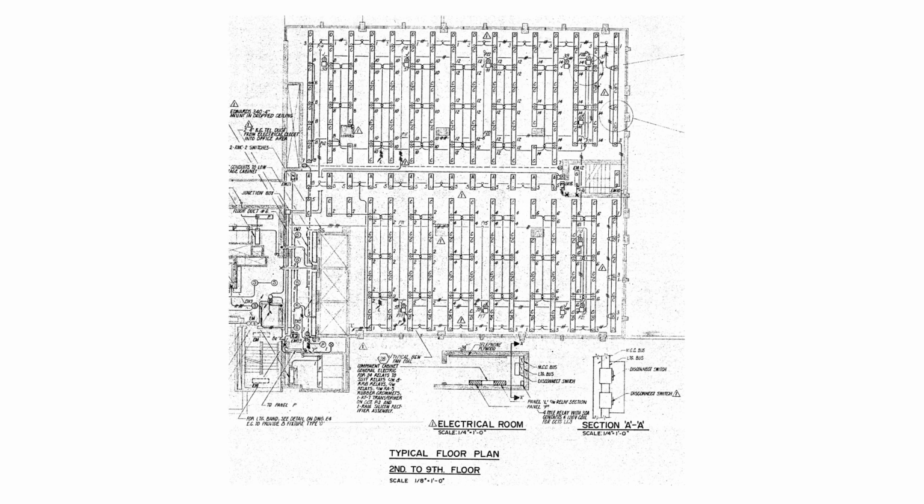So if you read the circuit number 14, 14 is the same number as the breaker, and it's the same number for the relay. So in the relay cabinet is the same circuit number. In that case, that 14 will do this group of lights here. Then there's another circuit, 12. 12 will do another circuit of lights.